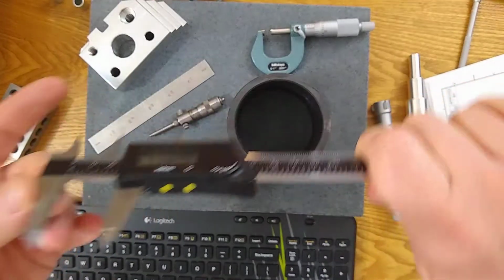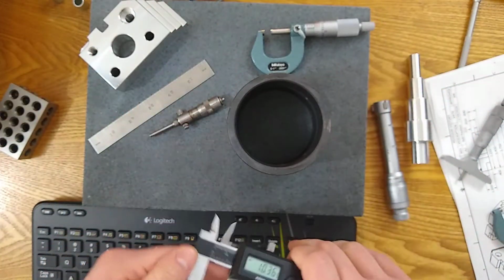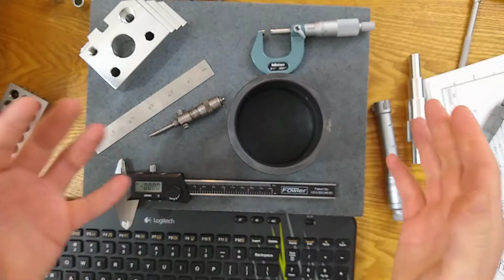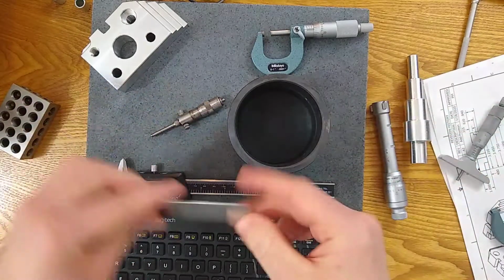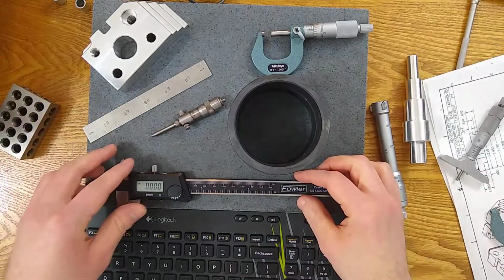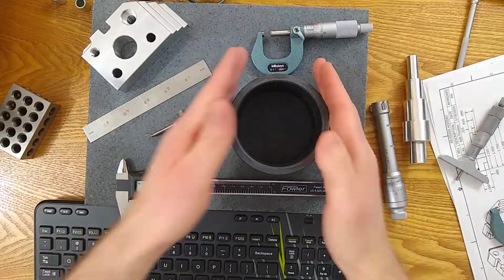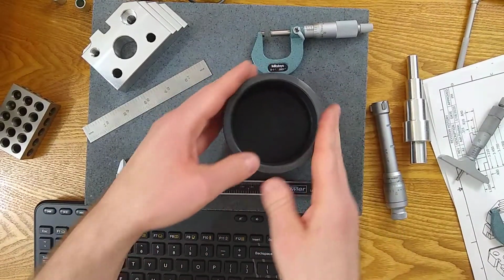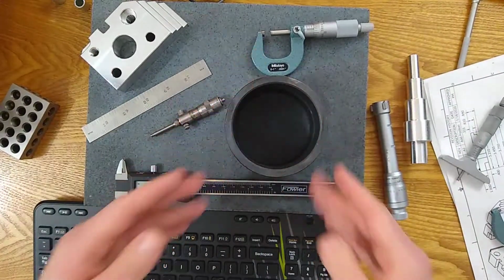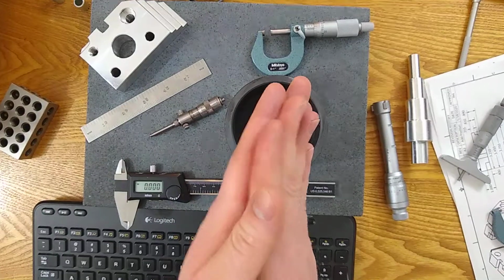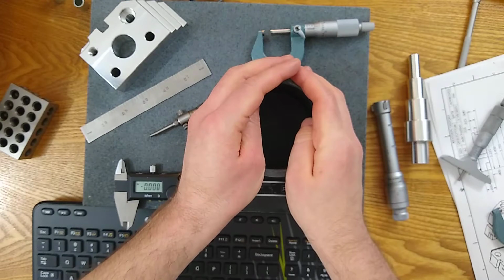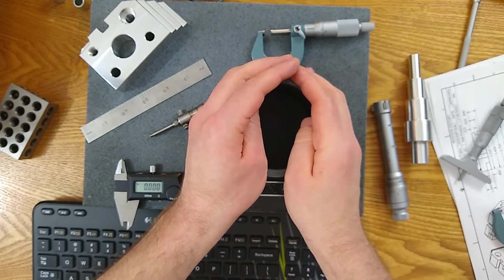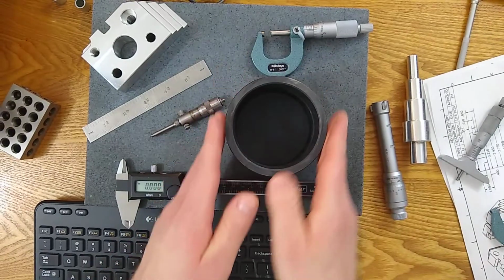You did everything right. You used a calibrated micrometer. You used it correctly. It's the same as using a scale. Could you really tell that with a scale? It's no different just because it's a caliper. So going above and beyond to verify it is what good inspectors, good production people will do. Verify your measurement. Make sure that the part is going to work for its function and be within spec. Some places don't do that, some do. I always do, if I'm right on the edge of tolerance, try to verify with something more accurate.